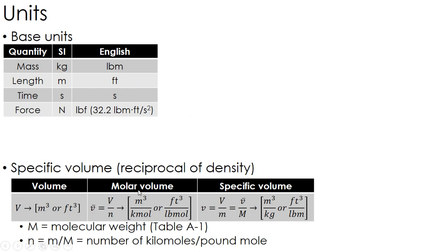Okay. Now, for those of you who have taken chemistry, we have moles. Now, this is another one where you shouldn't think too hard about this stuff. We don't do things in moles in thermo. We deal with things in mass form because that's how engineers think. We're going to weigh the thing anyway. We're going to figure out the mass, base everything on the mass. The difference between mass and moles is essentially the molecular weight of whatever substance we're looking at.